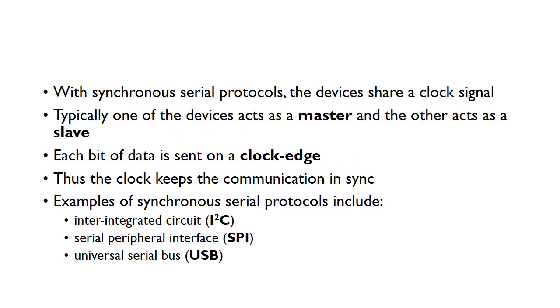With synchronous serial protocols, the devices share a common clock signal. Typically one of the devices acts as a master and the other or others act as slaves. Each bit of data is sent on a clock edge, so the clock basically keeps the communication in sync. Every time the clock ticks, one bit of data will be sent between the master and the slave or